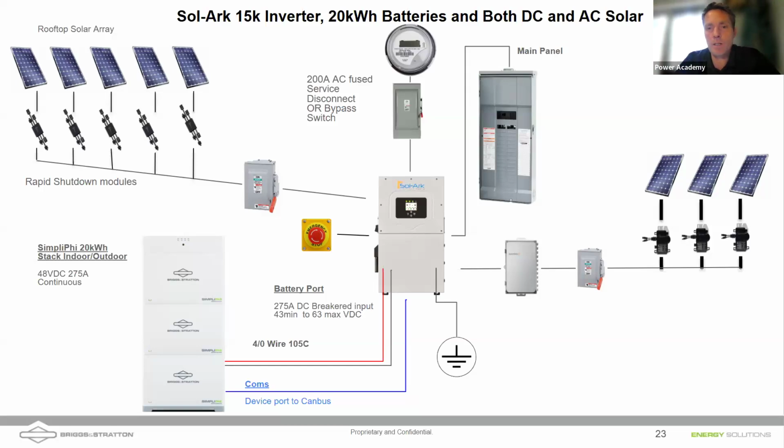When you do press that button, it shuts everything off. It shuts the keep alive signal off to the rapid shutdown modules, as Daniel mentioned. It shuts the loads off to the house and shuts the AC coupled panel down as well.